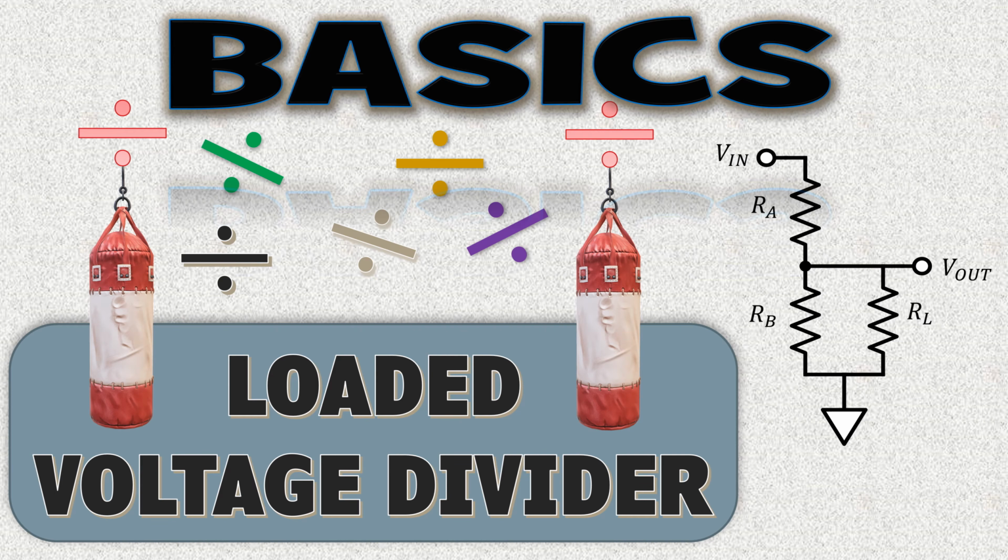One fundamental part of learning the most basic electronic circuit analysis involves the voltage divider rule. Most textbooks explain this as a circuit with two resistors in series with the output not connected to anything. Many circuit applications will have the output going to an input of an opamp, voltage comparator, or some other circuit with an input impedance that is so high that the effect of loading on it is completely negligible. However, this is not always the case.